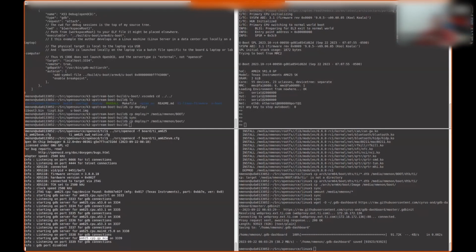Because they are network ports, you could locally debug A53, while your colleague in India is debugging the same board for the M4. Another colleague is debugging the R5. And if you like, yet another colleague debugging the TIFS core. So this gives you the flexibility of literally distributed debug. Now, most of us typically wouldn't use that. It is only when you hit this unique debug situation where you need multiple developers getting involved. It's only in that case that you need to do it.